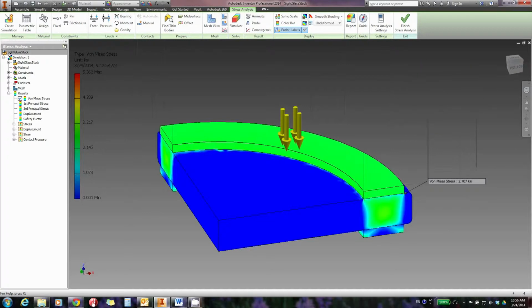Second, this tends to be a slowly growing crack rather than a catastrophic blowout. And third, this crack occurs outside of the process, so the crack out here won't cause any kind of a loss of containment, at least not immediately. And this is why people have been able to use this type of an arrangement for more than a century without serious problems. The rim fracture out here is usually not a life and death risk. Of course, you'll want to check that explicitly for your case.